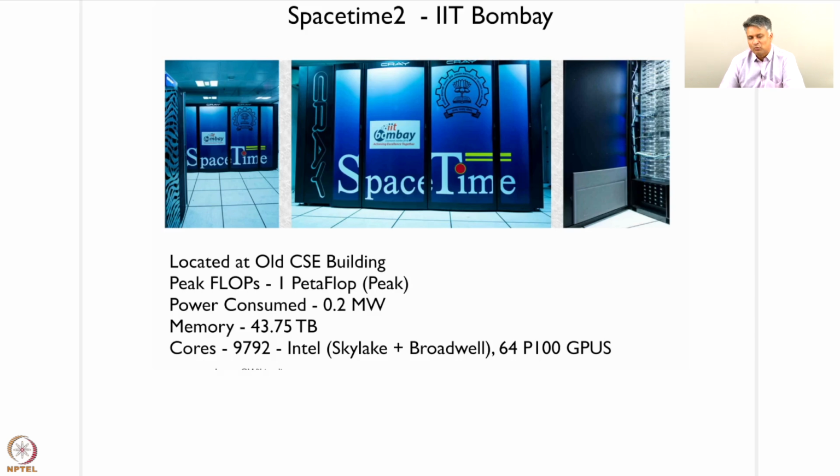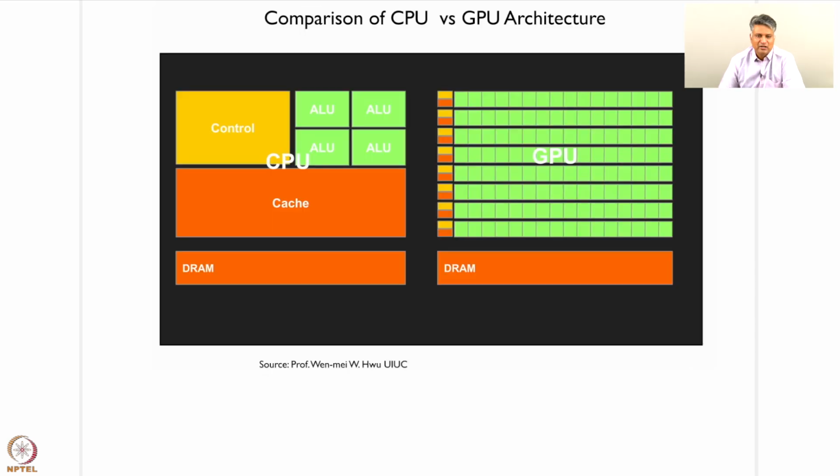So now the question is, what is the fundamental difference in the architecture of GPUs and CPUs? Which we will answer now. A CPU has several very powerful arithmetic logic units, but is essentially seen as a single core. It has a very large cache, it has a lot of capability, it has a variety of several heavy-duty instructions as well. Typically, CPUs can perform very complicated calculations by themselves without breaking them down into sub-instructions.